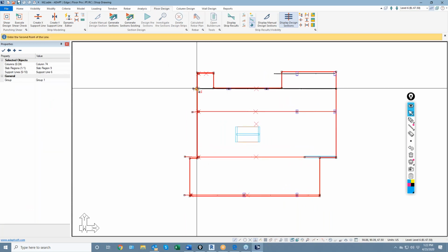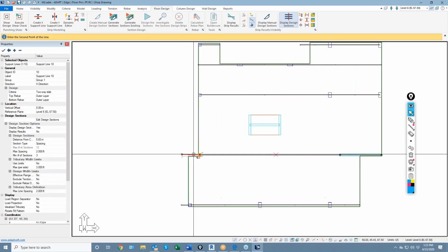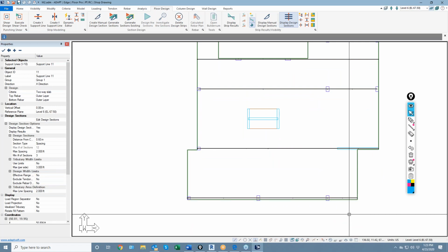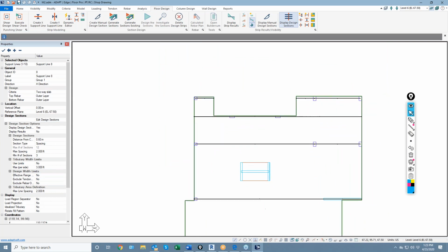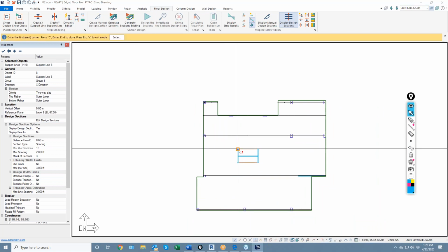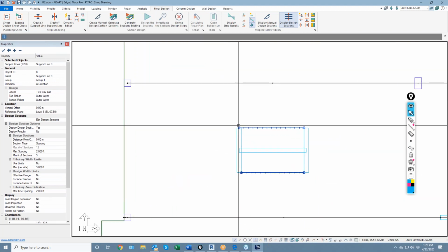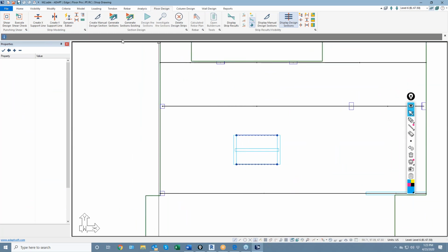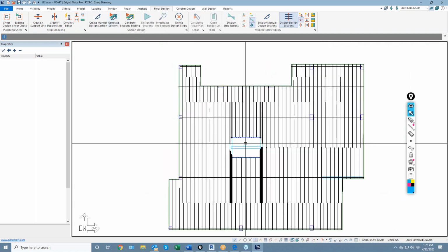The more strips you have, the more design cuts you're going to have, which means you'll have a more refined breakout of results in the slab per the strip method. You'll be able to refine the number of design points, or data cuts rather. So again, in this direction, we're going to use an X splitter, and I'll bound this opening off from the design cuts entering that area. And I'll generate my strips again. Okay, so this is the generation of the design cuts.